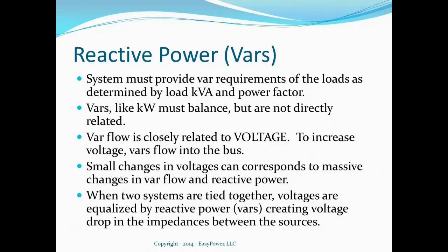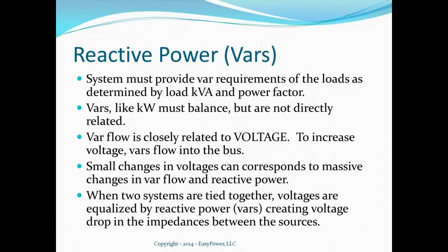The VARs we call reactive power, imaginary power. It's not real power. It's not real energy. It's a reflection of the phase angle difference between the voltage and the current, the power factor. But you can treat them as if it was a power flow, and that helps us understand what's happening in the power system. And like the kW, these must balance out.